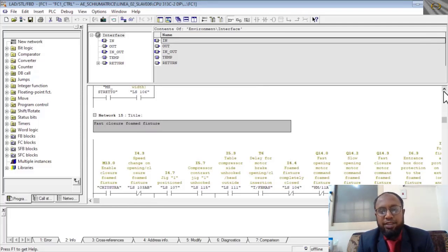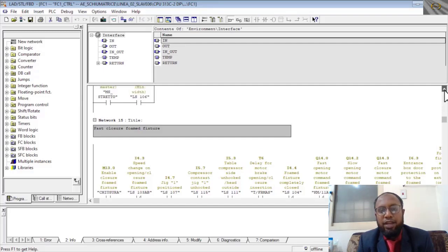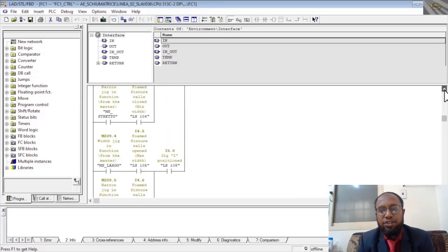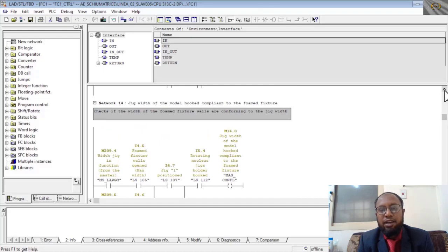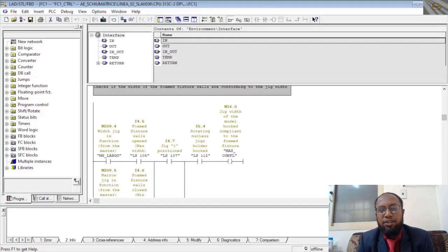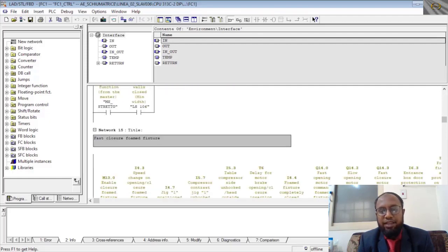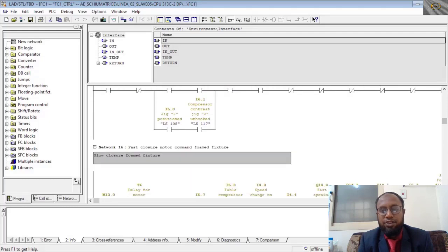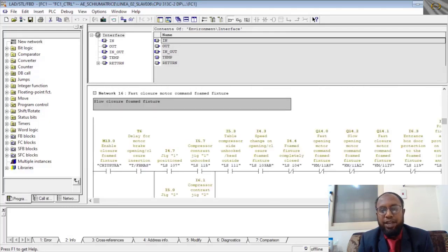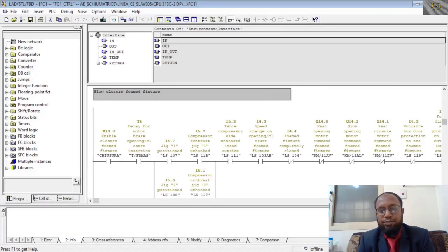That output we find first. Then we see the logic, which logic is active. Then this output will be on and our problem will be solved. First of all, we have to check the logics. Then we have to apply the conditions for the respective input addresses with respect to the output. This is the procedure for checking the input output address.